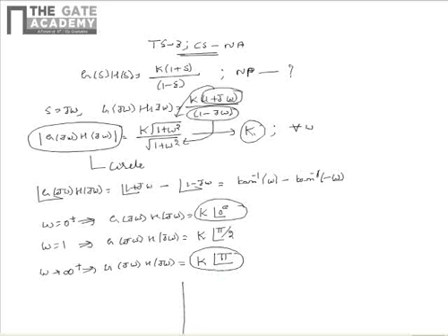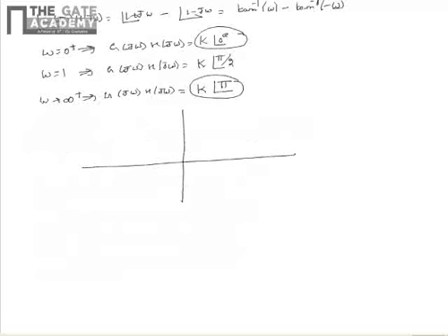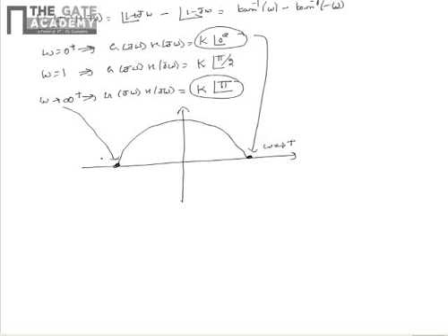So upon plotting the same in the Nyquist plane, that is G(jω)H(jω) plane, ω equal to 0+ corresponds to this point and ω equal to infinity+ corresponds to this point. We also see that the Nyquist plot is a circle because the magnitude is remaining constant at K. So this is the variation of the plot from ω equal to 0+ to infinity+.